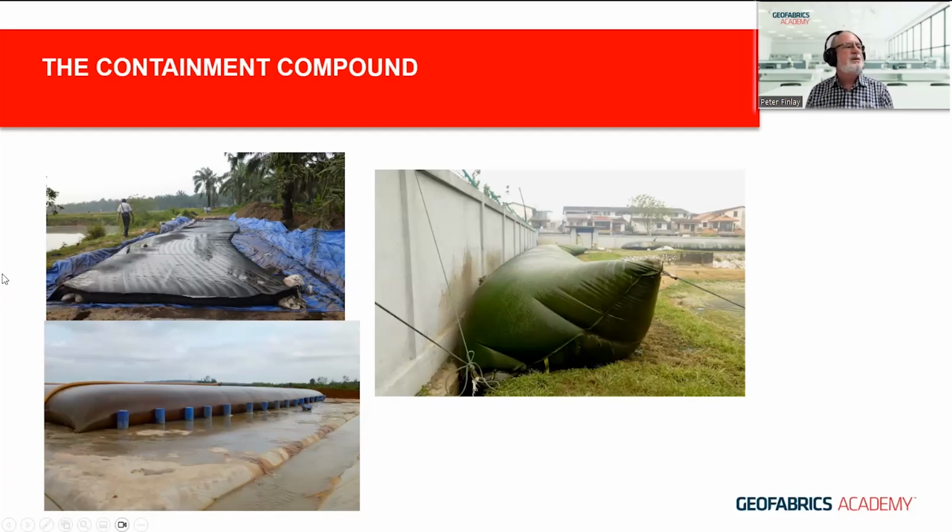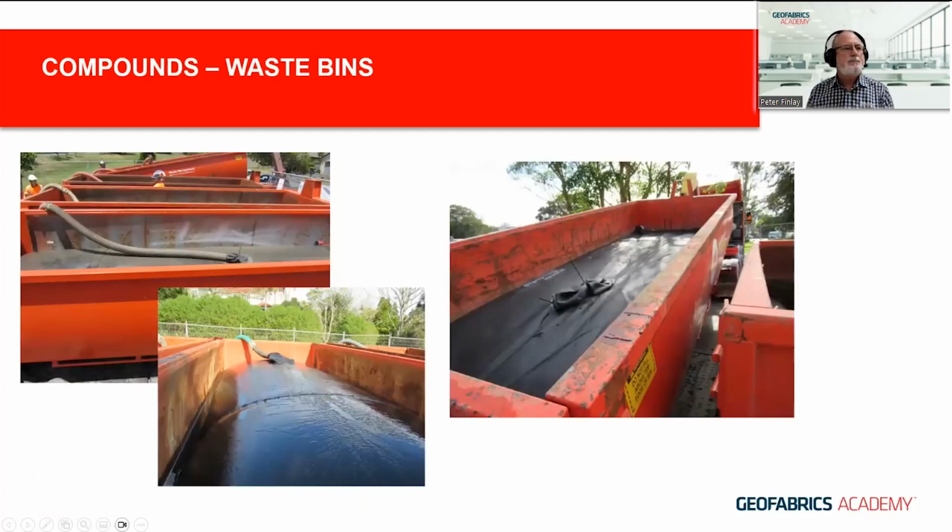So it's very important to get the laydown area as level as possible. There are things that you can do to help keep the geotube in place, but the best thing is to have it as level in all directions.